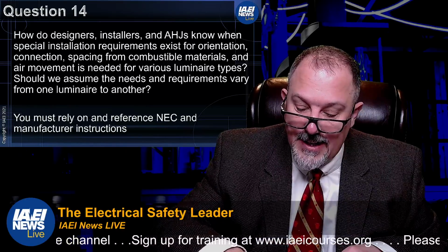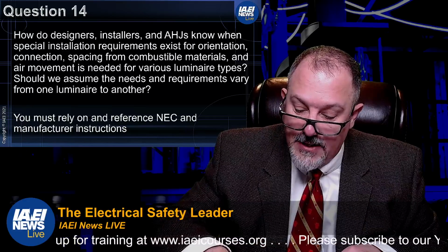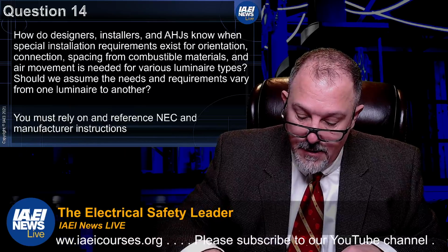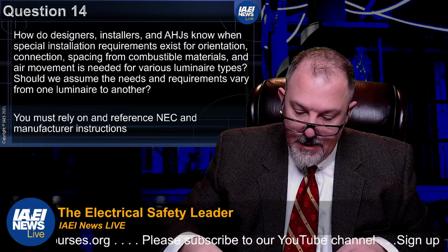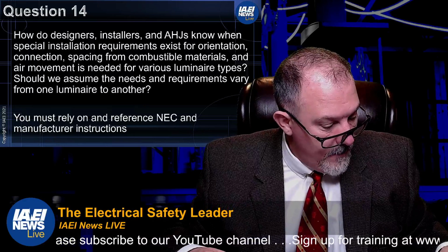Recessed high-intensity luminaires designed to be installed in wall or ceiling cavities shall have thermal protection and be identified as thermally protected. This stuff just keeps getting better and better, right?